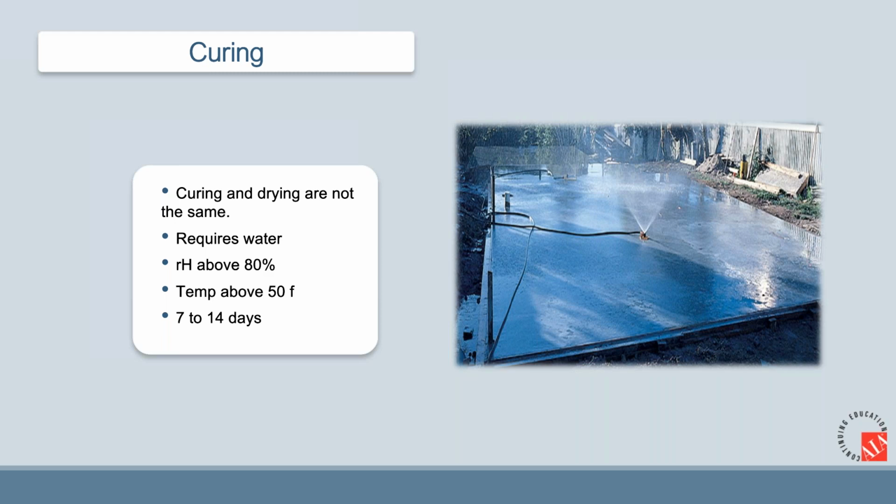So understanding that curing and drying are different is really, really important, because your engineering groups and your concrete people want concrete to be wet. They want it to be wet as long as possible. And on the flooring side, they're constantly asking for it to be dry. So it's really important that we understand the differences.